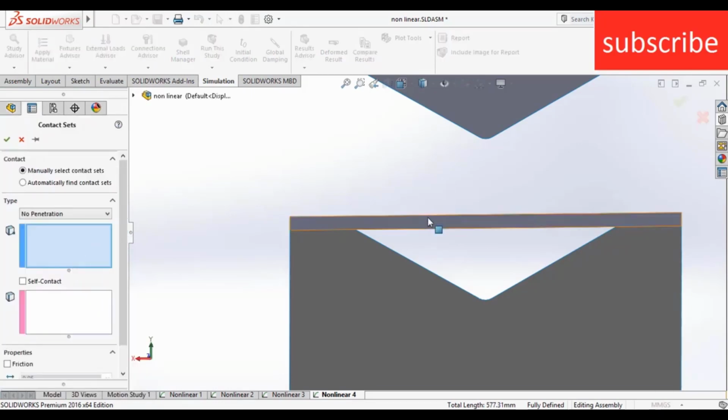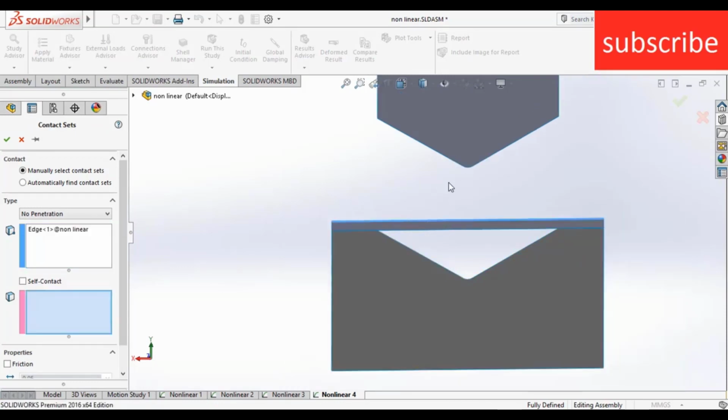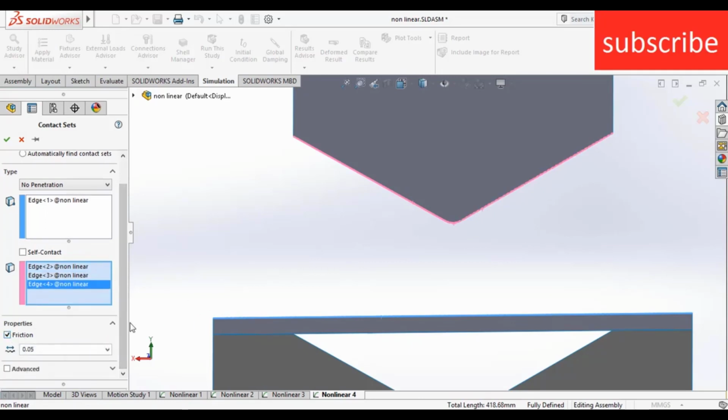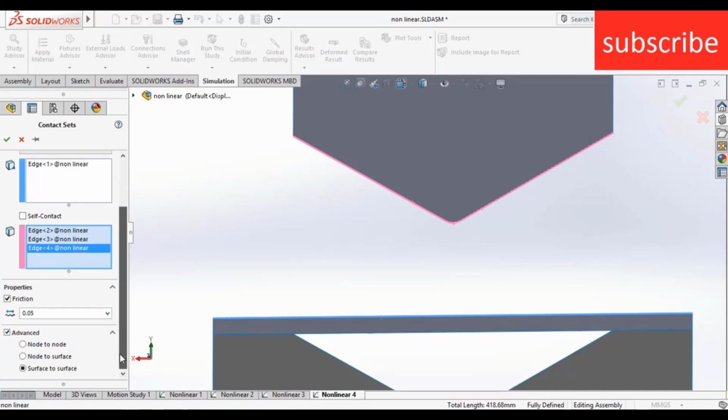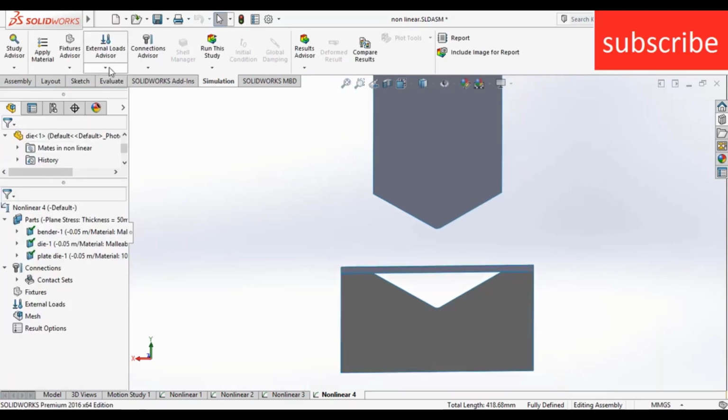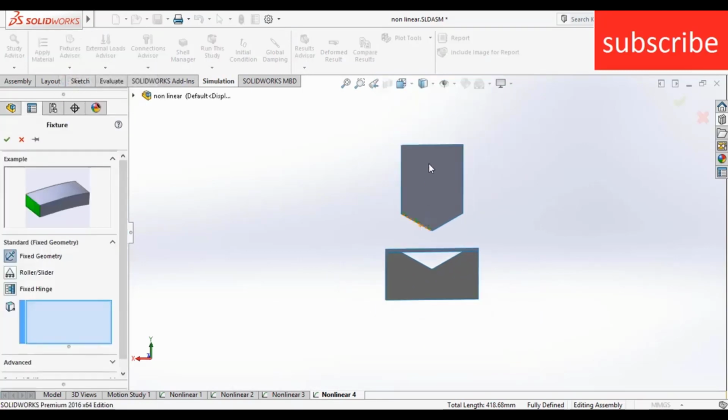Now this time we are going to create a contact set between the plate and the die that is going to bend it. Make sure you click all the edges. Click on friction. You can change the friction value as per your requirement. Click on advanced. Make sure it is surface to surface. Click OK. After that, what I need to do is go to fixtures advisor, click on fixed geometry, select this